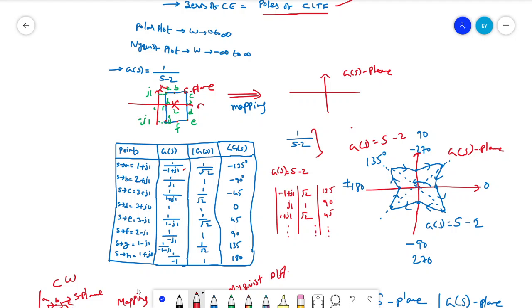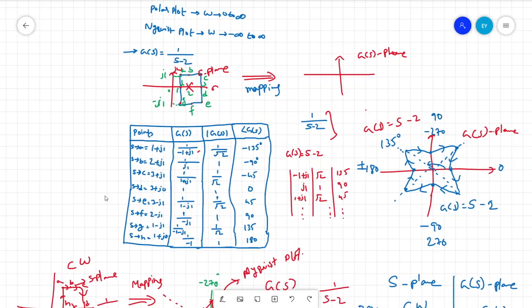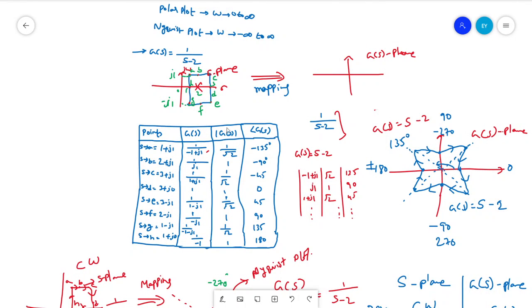Here I have given it in a table. You can go through this table, where we calculated the magnitude and the phase. How to calculate that? The square root of a squared plus b squared from the given transfer function will give the magnitude, and minus tan inverse of b by a will give us the phase. I calculated this and kept it here for this transfer function.